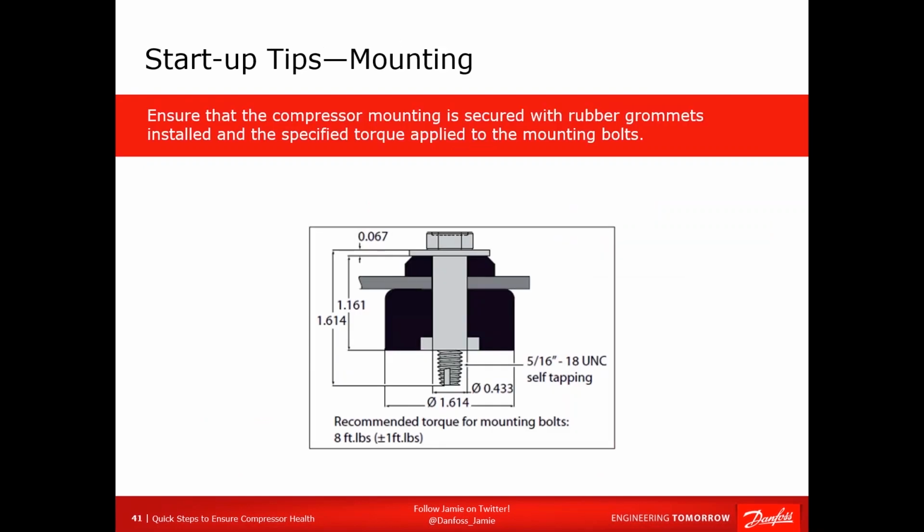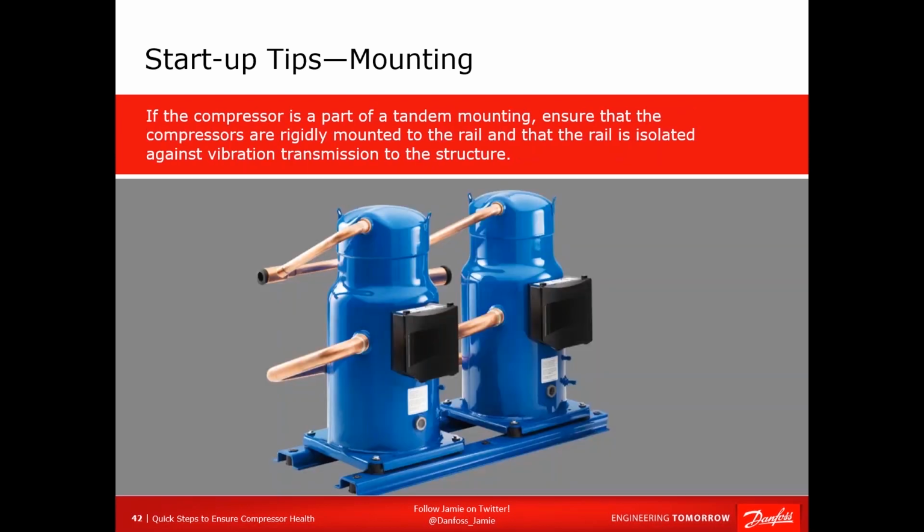Finally, some of the things people overlook. If you are starting up a new unit, the grommets on the compressor have probably all been torqued down. Bring them up and loosen them until they are torqued to spec value. It is very important that the compressor does not vibrate because you want to keep all the pipes attached to it.